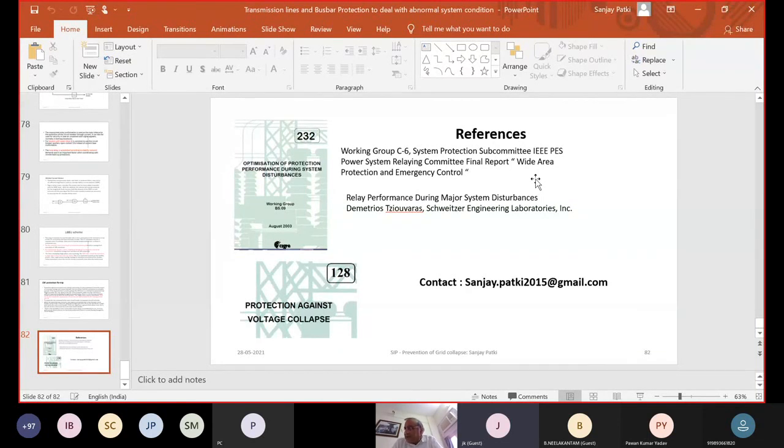Actually, these numerical relay measurement algorithms, I am not so familiar with each supplier's, because each supplier uses its own. This is basically what we call the frequency tracking phenomenon, because all the measurements are based on sampling, and there is a sort of repeatability check and security checks, so they need to have this frequency tracking algorithm.